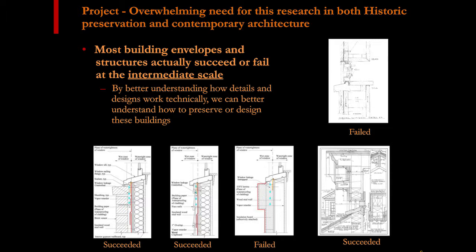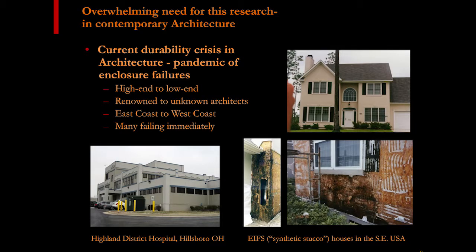So, from where you're sitting, you probably have no idea why half of these failed and half of them succeeded. And that's exactly the point: you really have to look at these closely and get into the exact details of how this flashing overlaps that felt or Tyvek or whatever else, in terms of how these are going to hold up over time. So it takes very detailed focus.